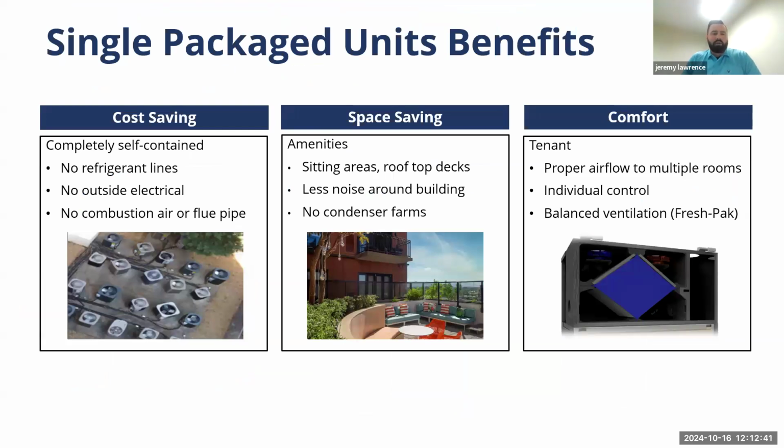The advantages of packaged units is the cost savings, right? These units are factory built. There's very little startup to do. There's very little that can go wrong. There's almost nothing that the installer could do to cause a problem that would affect its operation, right? When these units get installed, they've been factory tested, shipped, slid into the sleeve. And if there's anything wrong with them, it's up to the manufacturer to really get them up to speed. There's not a lot for the contractor to do.